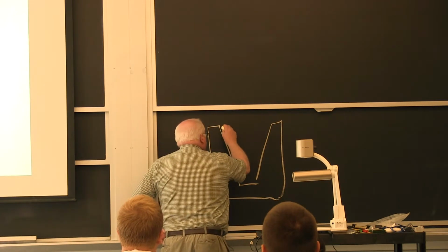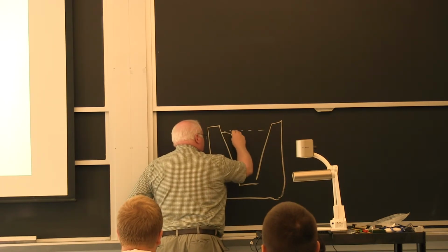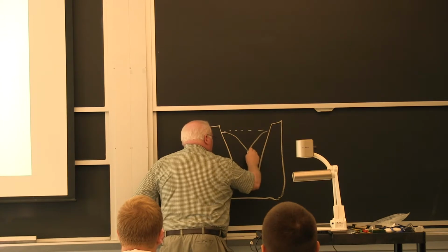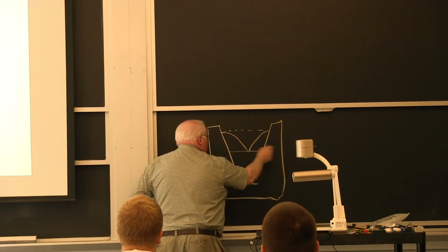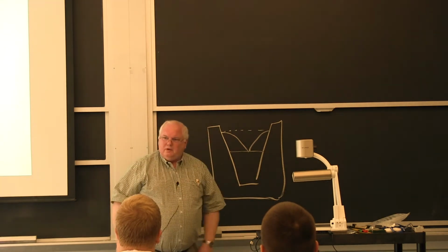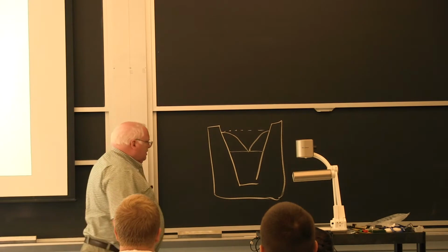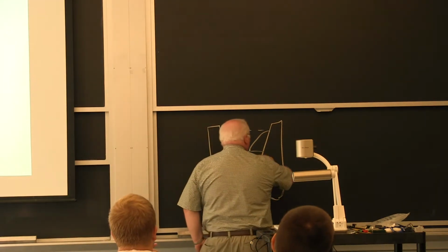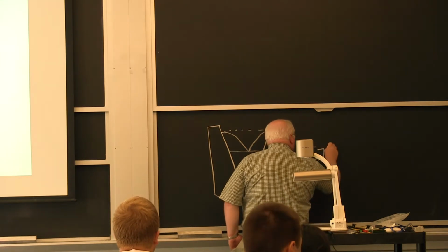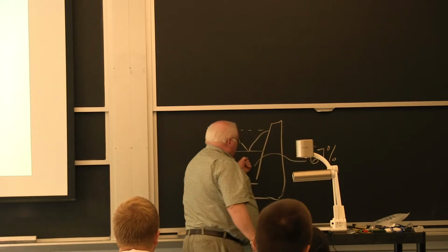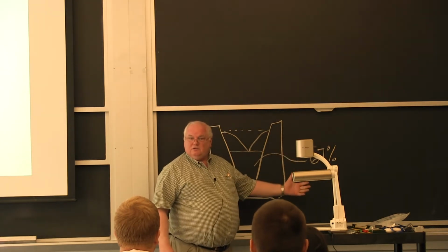I pour the steel in at that level, but as it solidifies and shrinks, I get what we call a pipe, and when it's all solidified, I've got to cut off 1/3 of the top and send it back to remelt it. As a result, my yield when I was at Bethlehem Steel in the mid-80s was about 67% of tons poured versus tons shipped. We called that the yield.